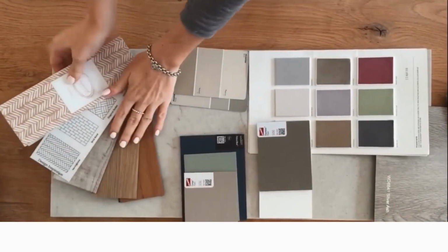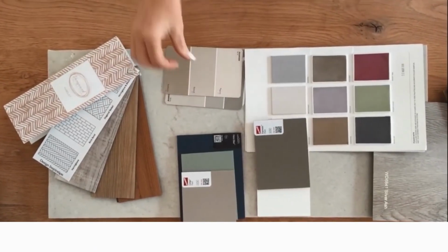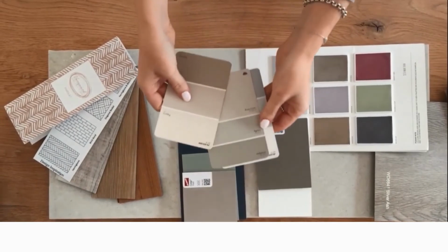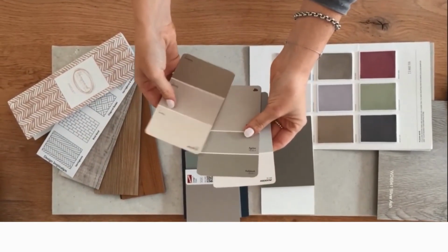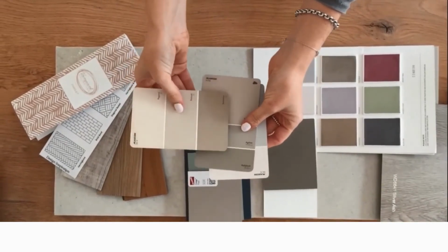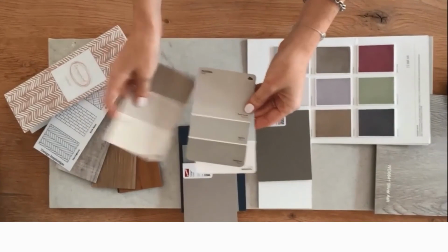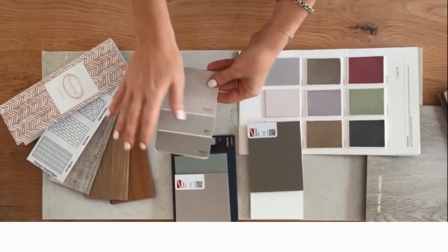Do you see how I've used the factors influencing our finish to describe my floor finish? Well, that's important to do on every project with every finish. Consider every element influencing that finish, how it's going to be applied to the space. What is the client's budget? Is there weather that's going to influence that finish? What is the traffic zone? How many people are going to interact with that finish? All very important elements to consider.